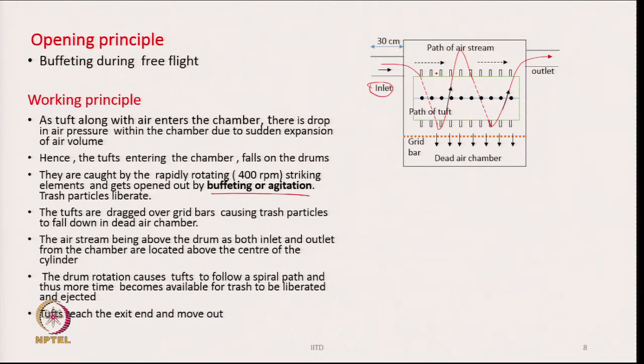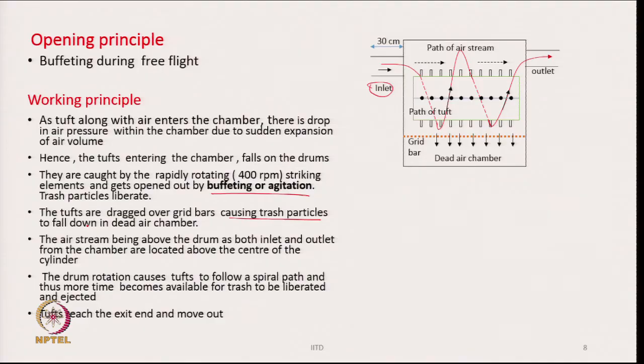The tufts will be dragged over the grid bars, causing trash particles to be liberated, and it will also cause some trash particles to fall down. Since they will be thrown by the centrifugal force, trash particles will be falling down also, and at the same time there will be scraping action as the tufts are dragged over the grid bars. So, a lot of scraping action will be there, a lot of trash will be liberated, and some of it will also fall down.